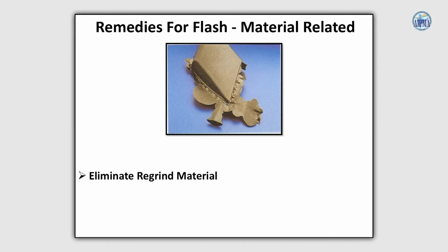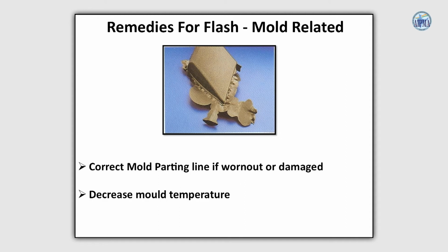Remedies, raw material. Eliminate regrind material. Remedies, mold. Correct mold parting line if worn out or damaged. Decrease mold temperature.